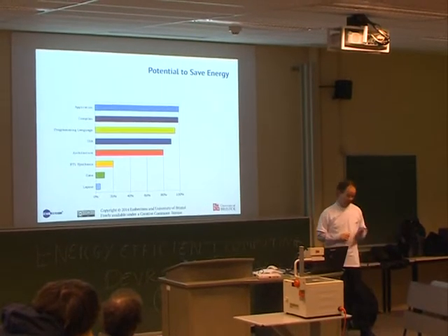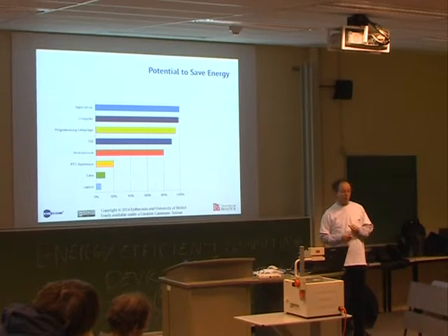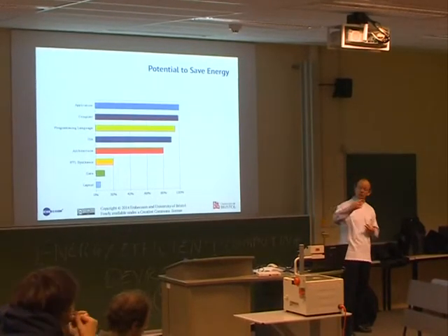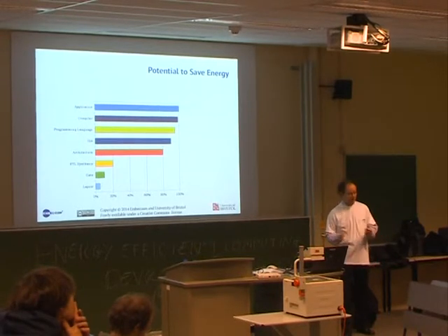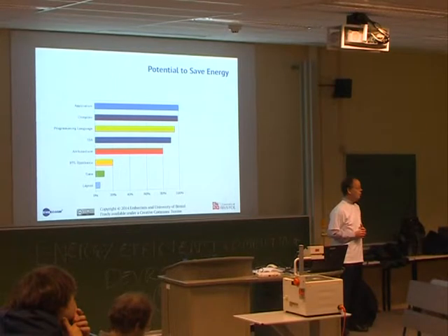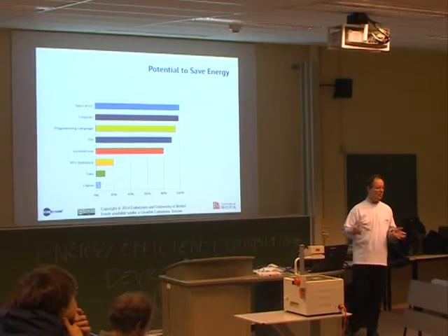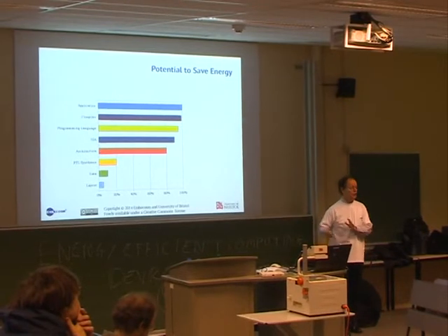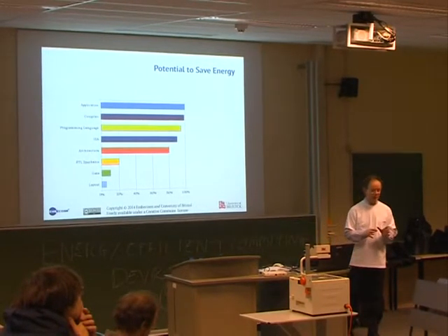So the best part of a milliwatt. Now that's pretty efficient, but if you don't need the compute power, if actually you only have to do the occasional little bit of sensing, you can run it at 32 kilohertz. At that low frequency, you can drop the voltage to 1.8 volts, and then it'll use 4 microamps at 1.8 volts. So that's about 8 microwatts instead of 1 milliwatt. Huge potential there. And that's been achieved by the hardware guys.